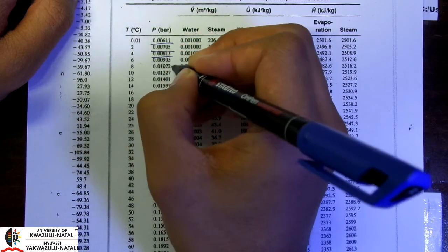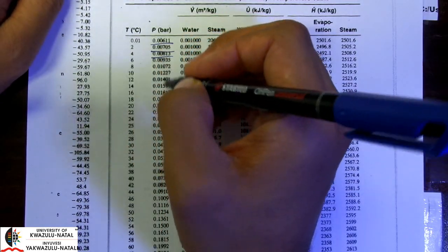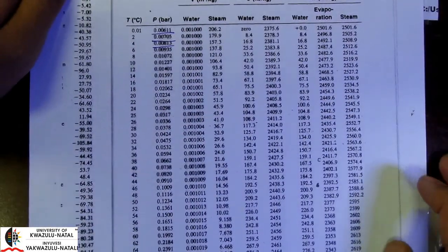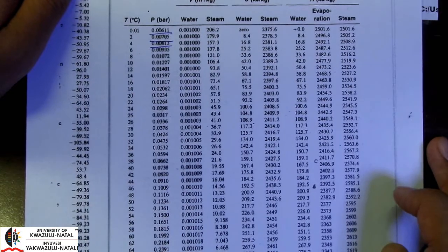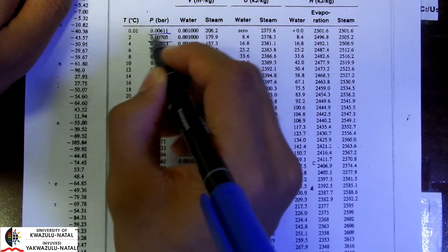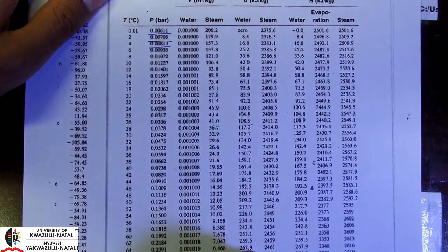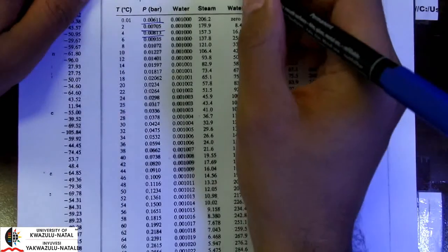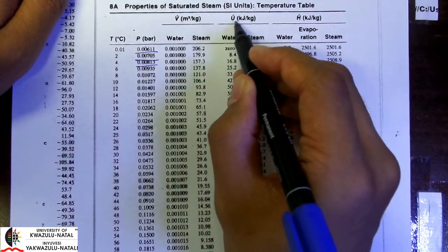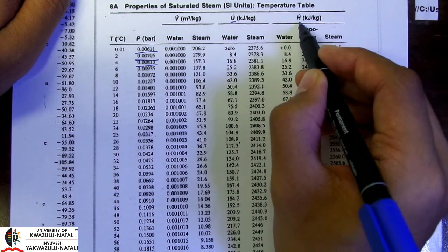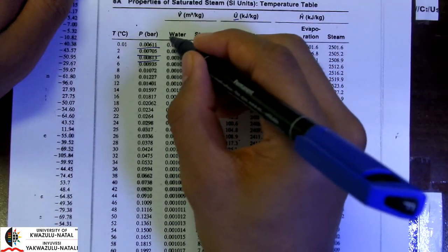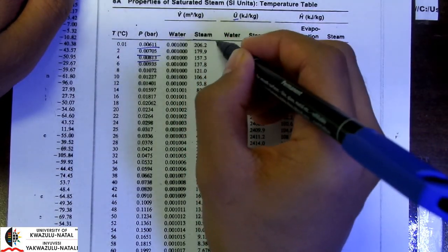Okay, so this is the pressure required to keep our liquid water a liquid. Once we pass this pressure, we will of course obtain water in the form of vapor. So this is at saturated conditions, saturated pressures and temperatures, for various temperatures with an associated pressure. And we are typically given our specific volume, our specific internal energy, and our specific enthalpy, given in terms of saturated liquid and saturated vapor.